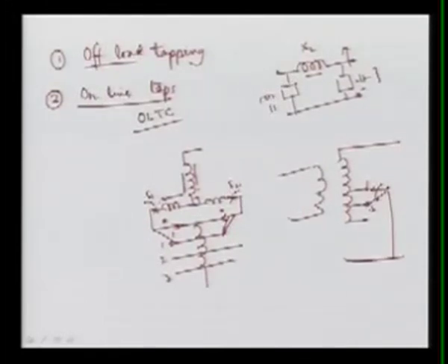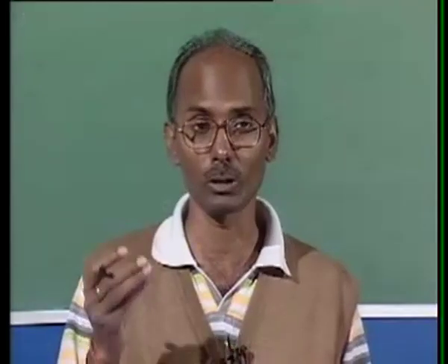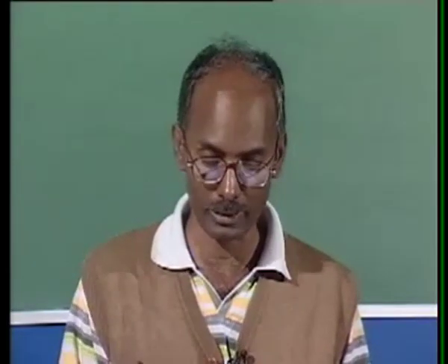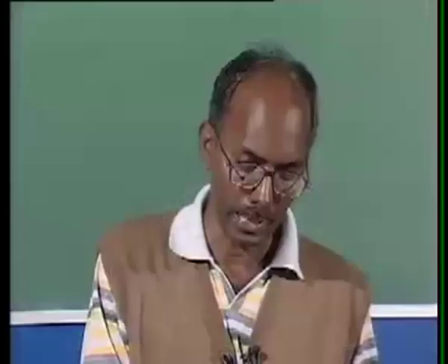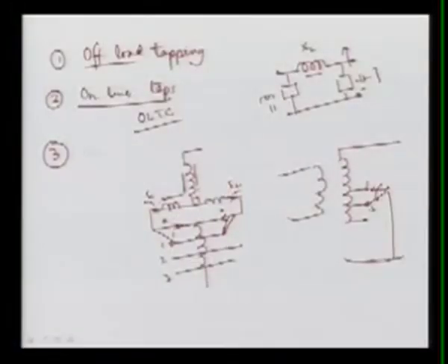At least 6 to 8 operations are required, and then we can move to the second position, and there is no need to de-energize, which means in working condition we can change the tapping. This is called your online tap changer transformer. Another transformer is also called the booster transformer.